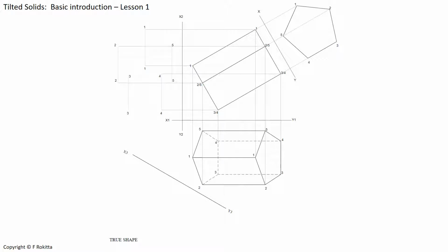In order to draw the right side view, we need to observe the front view from the right. This will help us to determine which parts of our right view will be hidden and which parts of it will be shown in full. We also need to start with our projection of the right view exactly the same way that we did with the top view. And that means we will need to start with our auxiliary view, and we are again going to apply the rule of measure, skip, measure.